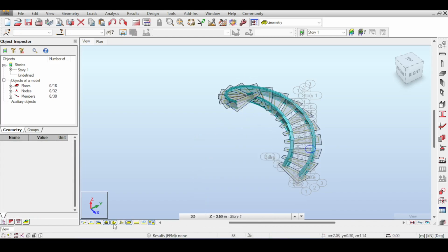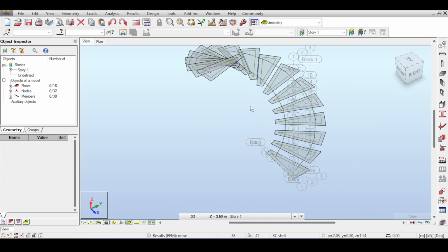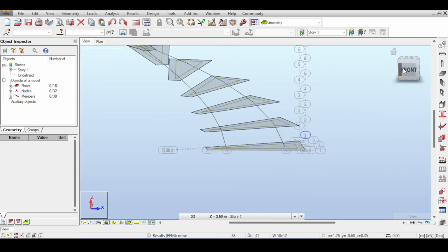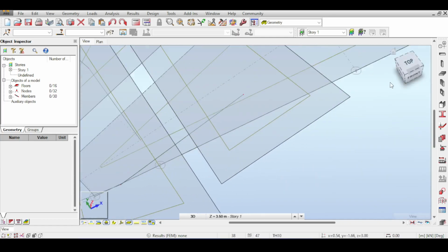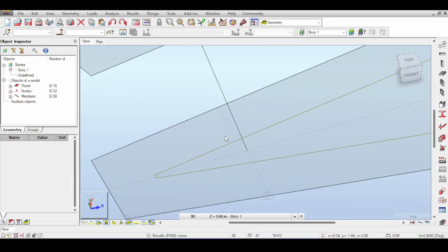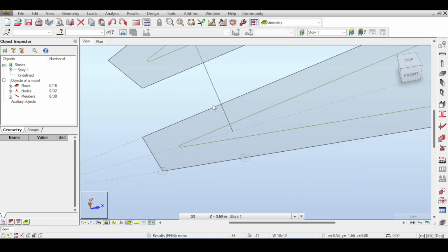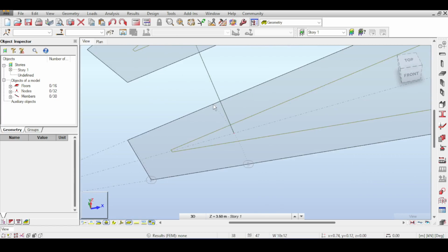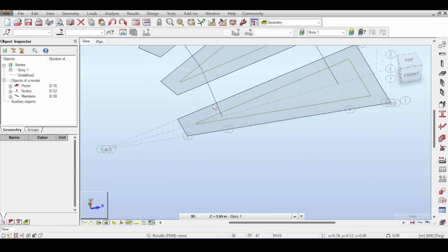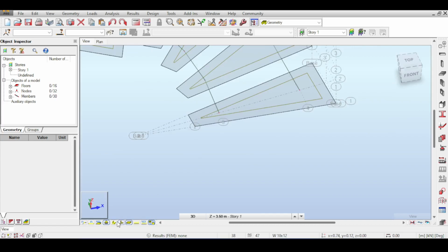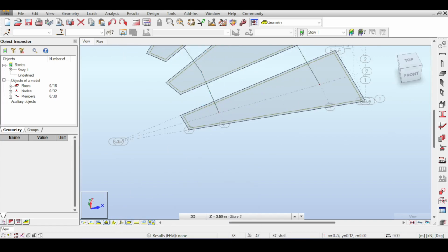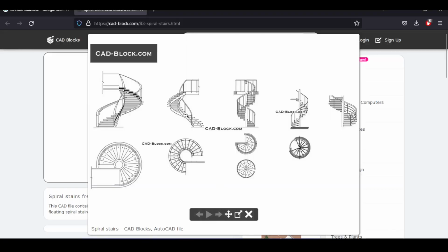You can change that. But before you change anything, now some of you might be really annoyed because they would think, hey, wait a minute, you are basically supporting it on the middle point here, but I want to support it here. Well, that's no problem. The only thing you have to do is to put your node here. If you put your node here, you get the support you want. You get the helical beam to be supporting on the edge rather than in the middle. However, looking at this, you can see that those stairs are somehow supported, especially here.